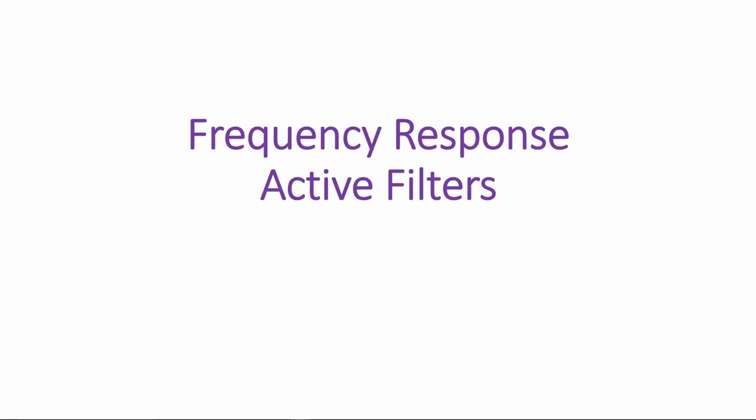Now combining the gain or the amplifying property of the op amp together with the filtering property of RC and RL circuits, we can create what is known as active filters. These filters are called active filters because they not only allow you to tune the frequency you want to select, but also allow you to apply a gain to it. So let's get started first by looking at the op amp circuit.